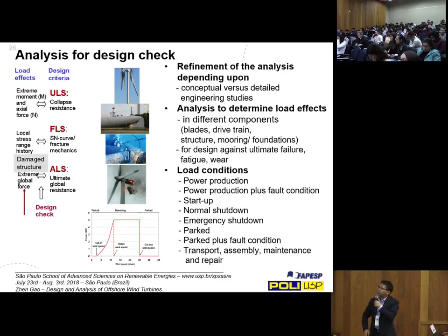Yes, and for wind turbines, we have to run analysis for many different wind and wave conditions. As I mentioned, the wind speed changes over a long time, and wave height and wave elevation also change over a long time. And then you have to do this analysis for all possible combinations during the design lifetime. There are also different load conditions that are considered for operation of turbines.